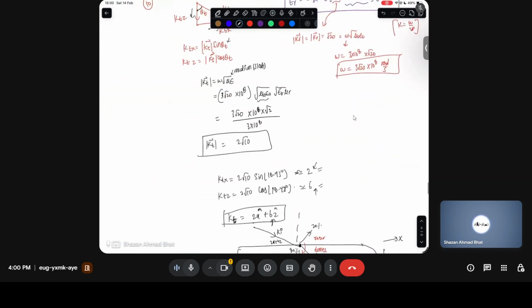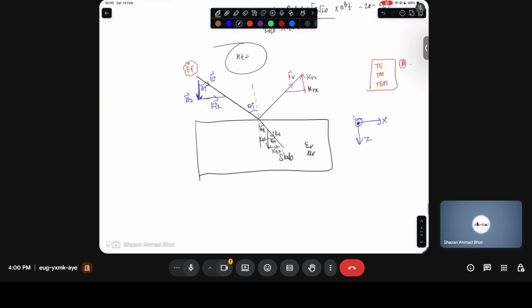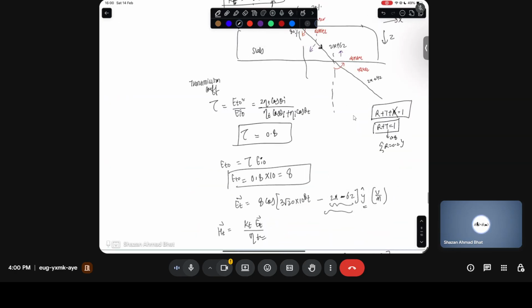Now if you draw the same magnetic field vectors over this figure, it's going to get messy. Then you need to show the x direction of magnetic field, y direction of magnetic field, it's going to make this figure messy. So what you do is that at a time, take one of the directions and then go forward with it, but do the calculations based on the electric field, the magnetic field, and remember the impedances, which is basically the impedance of this medium, the impedance of the transmitted medium, which are important, and that's how you are going to approach this particular problem.